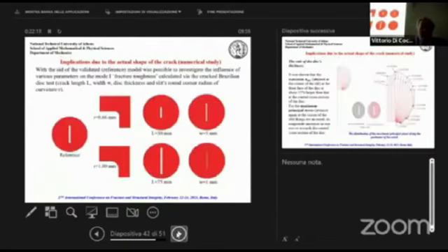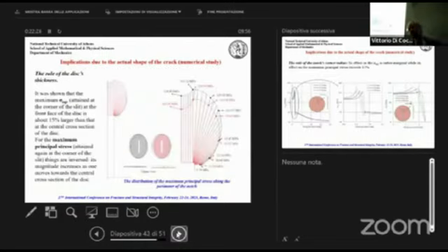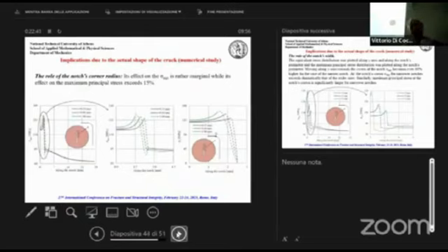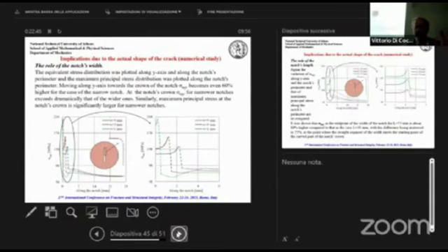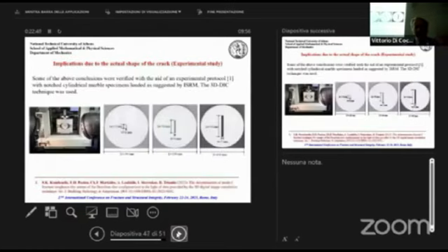So we made an analysis of the various factors that influence the stress concentration factor. And the most disappointing one is that our solution cannot take into account the third dimension. Since we use complex potential techniques, which are two dimensions by default, we ignore the actual stress distribution along the thickness of the disk, which is by no means ignorable. And then we made a thorough analytical parametrical analysis, but the details are more or less expected.